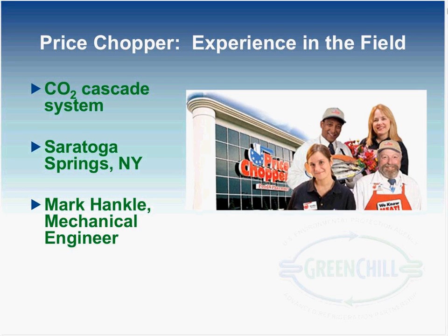There is some fear, quote unquote, of that technology. I think second would be the CO2 secondary. It's not quite as complex when you're actually looking at the racks. There is a little bit of hesitance from the tech perspective on the Cascade side, because if you look at those racks and the controls and the set points, the first time you look at it, it becomes a little bit overwhelming. But as the techs get more familiar with it and understand it's just a refrigeration system, if they get out of their mind that it's CO2 and not a traditional refrigerant, they seem to get very comfortable with it very, very quickly.